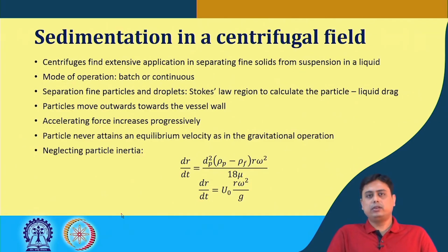So, sedimentation in a centrifugal field employs the second application of the centrifugal field. Here the centrifuges are basically used to enhance the sedimentation rate that typically happens under gravitational conditions. To enhance that settling rate, this finds extensive applications in separating fine solids from a suspension in a liquid. It can be operated in batch mode, or with appropriate associated accessories, it can be operated in continuous mode as well.